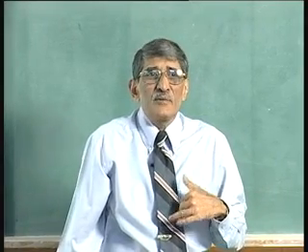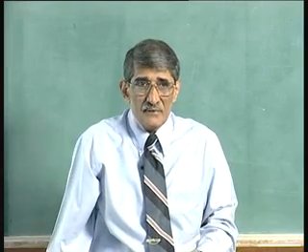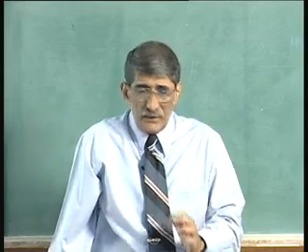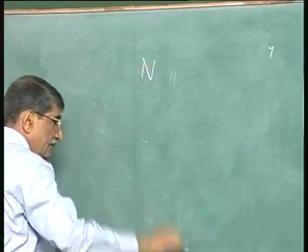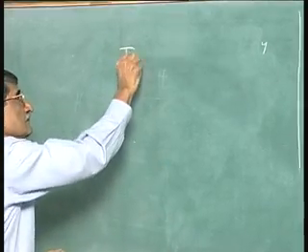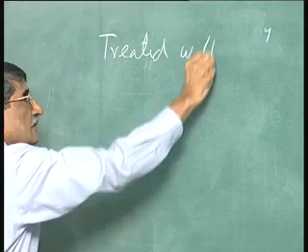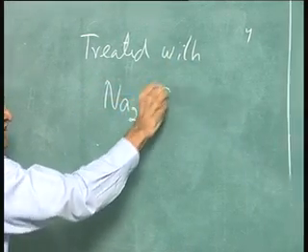At least a couple of PhDs have come out of our laboratory related to this area, in passivation and making MIS devices. So, what they did in Bell Lab was they treated it with sodium sulfide, Na2S 9H2O.